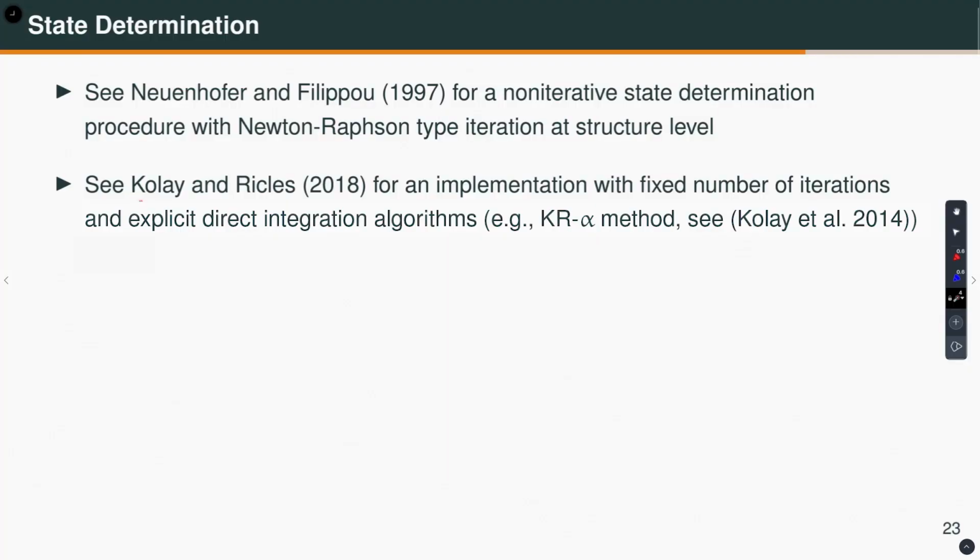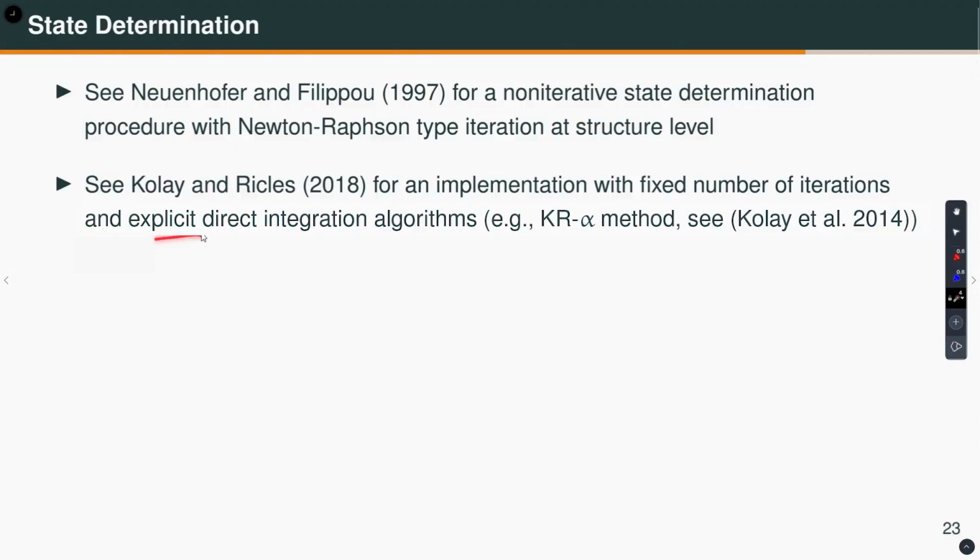So, I have also done some work on this. We have developed an implementation with a fixed number of iterations for using this with an explicit direct integration algorithm. Towards the end of this course, I will discuss the direct integration algorithms for nonlinear dynamic analysis. Okay. Here also you are not doing any iteration at the element level, and since we are using an explicit algorithm, there is also no iteration at the structure level, and this works quite well.